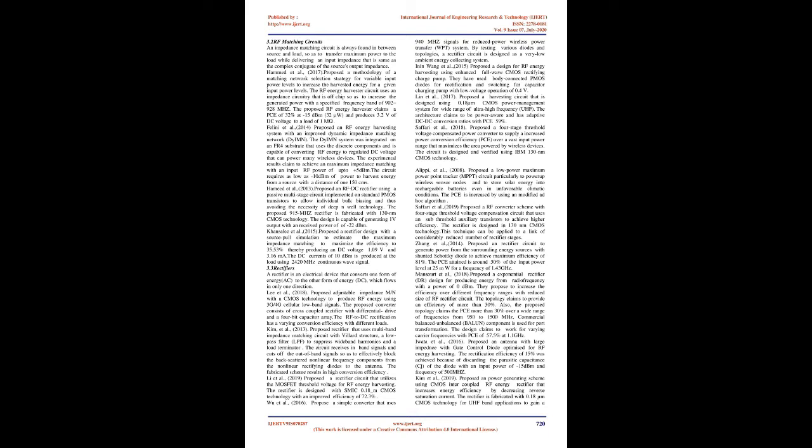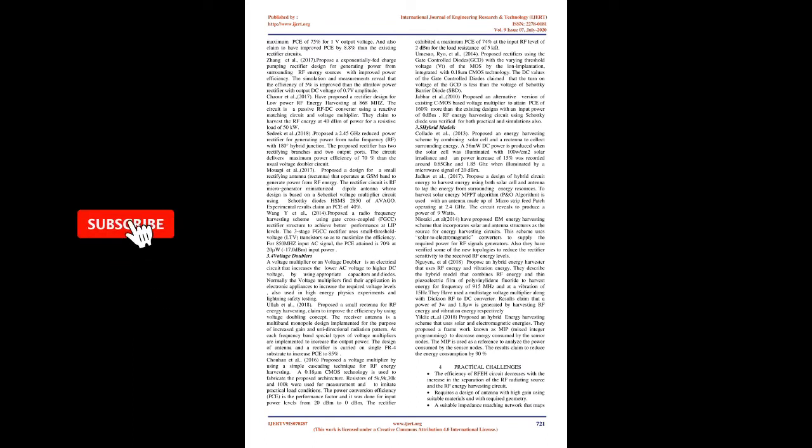Ghosh et al., 2014, proposed an RF energy harvesting system that is capable of powering tiny wireless sensor nodes using the electromagnetic radiated energy from cell towers operating for CDMA and GSM bands. To harvest maximum energy from the radiating towers, a special type of monopole antenna with microstrip is designed that has an impedance of 377 ohms, with circular polarization.